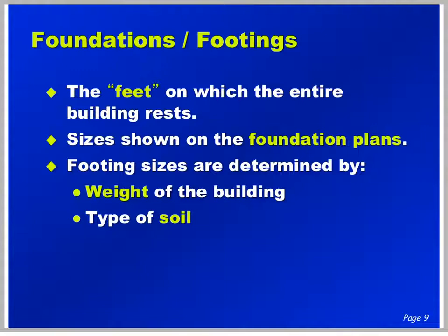Going back to footings and foundations. Foundations are the feet of the building, on which the entire building rests. They are shown on foundation plans. The footing sizes are determined by the weight of the building, how the weight is distributed onto the footings, and how the subgrade is able to resist those forces.